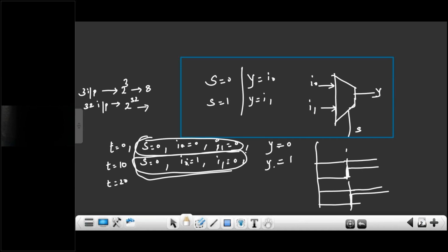All zeros, all ones, alternating zeros and ones, and random. Yes, that is for this example. For bigger examples, you have to decide intelligently what type of test cases to use so that the entire functionality is covered for bigger circuits, and all the lines of the RTL code are executed.